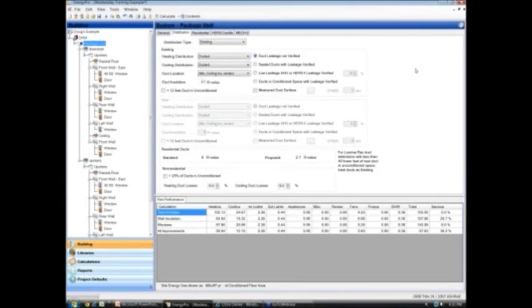So if I have a 50,000 BTU furnace, it's going to be 50 times 21.7, which is 1,085. I did that in a calculator. So that's my CFM assumption for that unit. If it has cooling on it, always use the cooling value of 400 CFM per ton, per nominal ton.